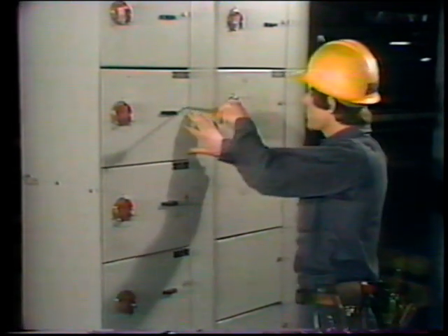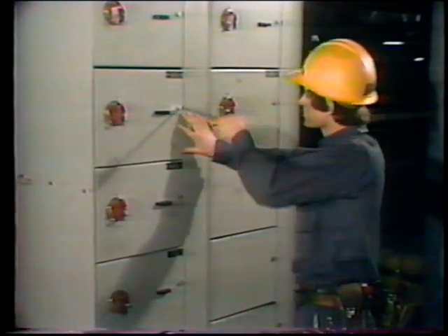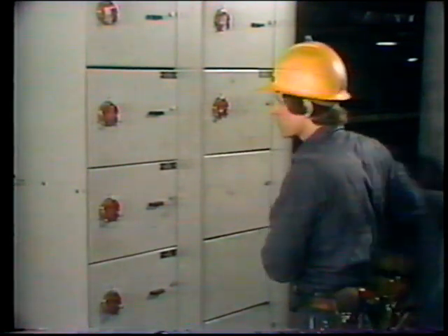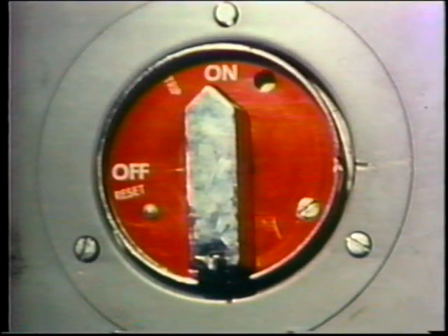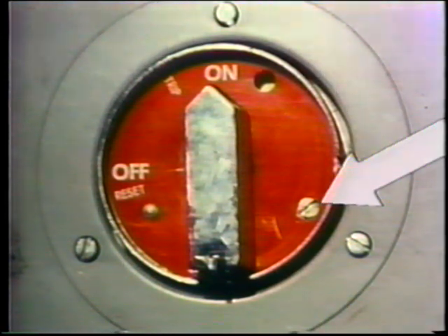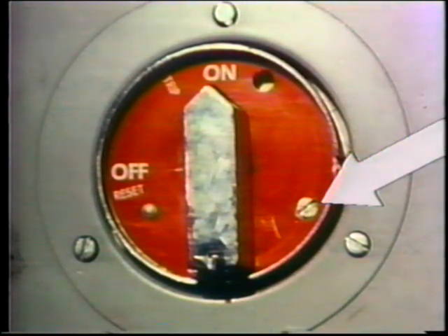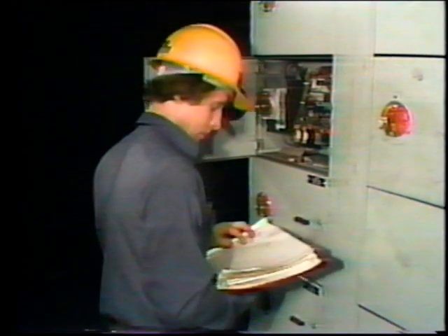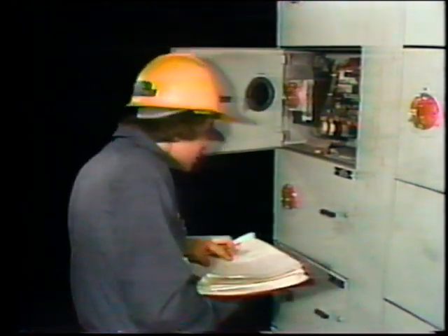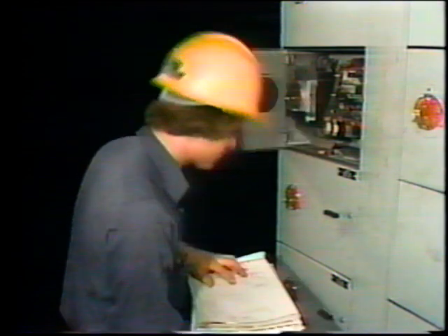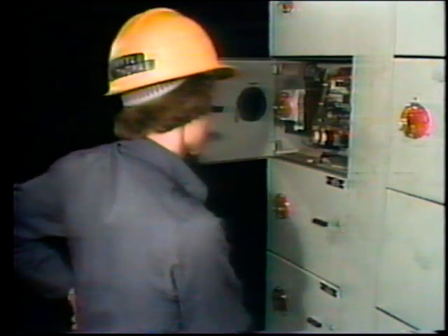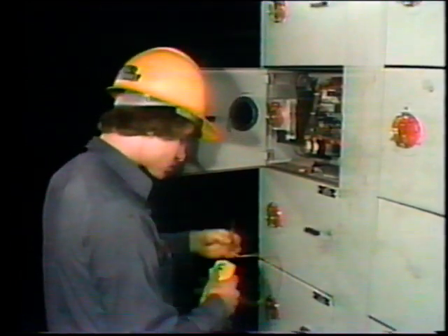He turns a screw on the right side of the cabinet. But this alone does not open the controller cabinet. This particular controller has a mechanical interlock that prevents the cabinet from opening when the controller is energized. When he turns the screw on the left side of the cabinet, the mechanical interlock is defeated and the controller cabinet can be opened. Next, he uses a wiring diagram to locate the fuses in the controller. Then, using a voltage tester, he takes a reading at each fuse.